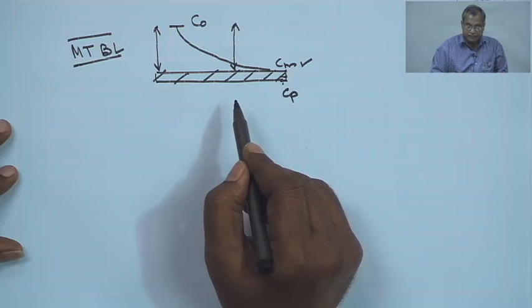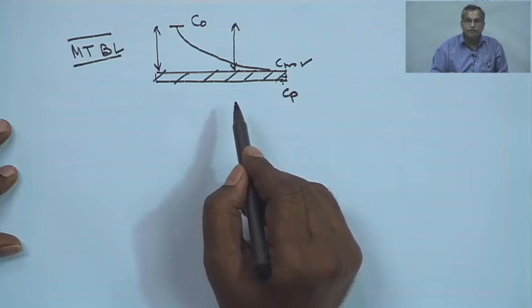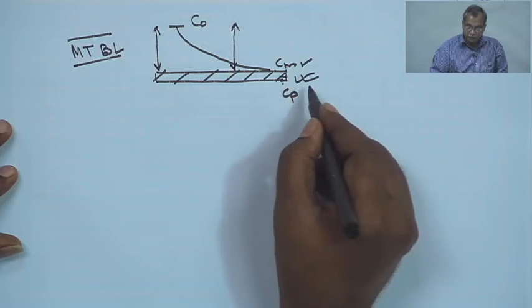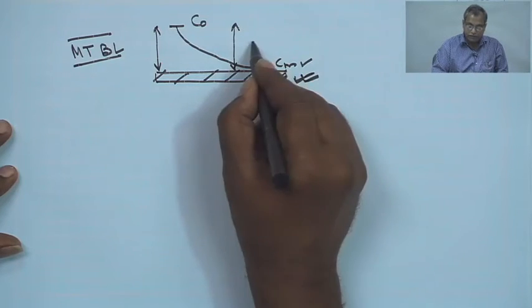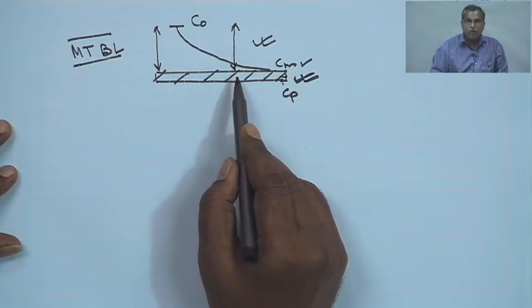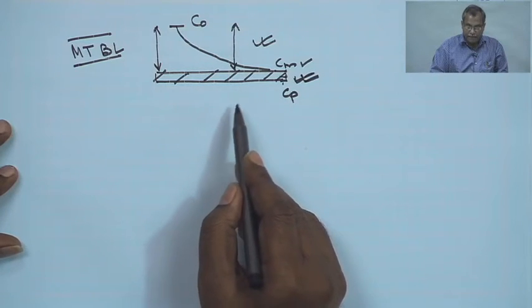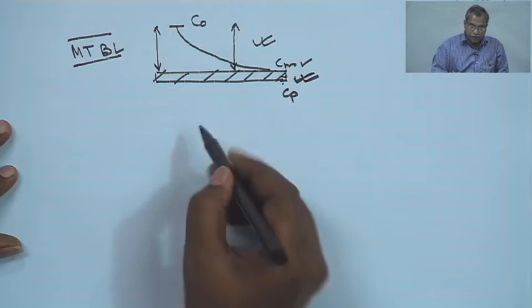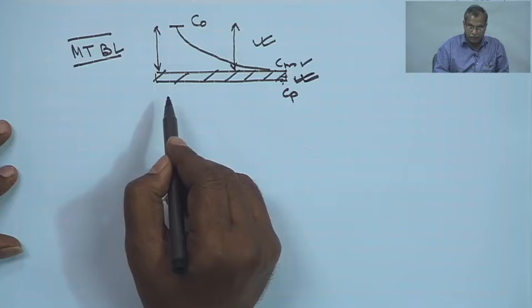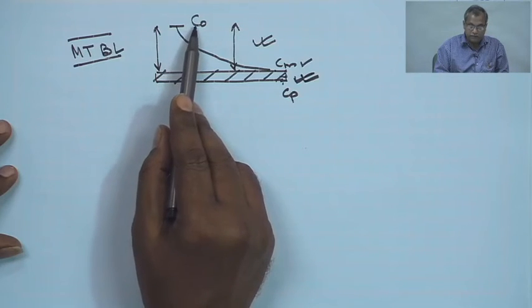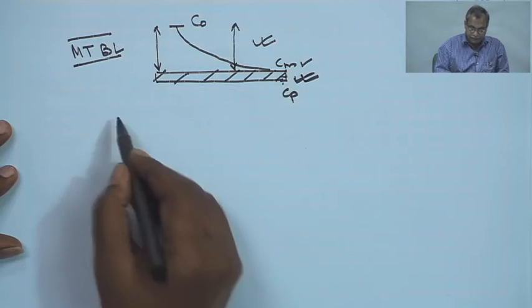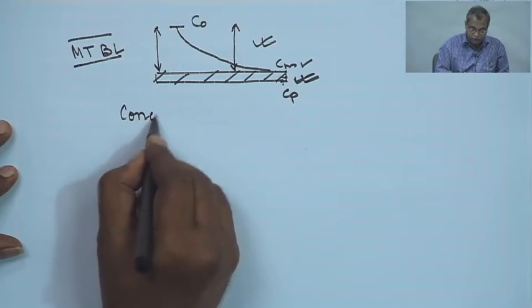In fact, there are two resistances involved in this process. There are two media involved in the process. One is the membrane surface, one is the mass transfer boundary layer. These two are placed one after another in series, and these two will be considered. So, the polarization of the solute over the mass transfer boundary layer, ranging from concentration C_0 in the feed to C_m on the membrane surface, is known as concentration polarization.